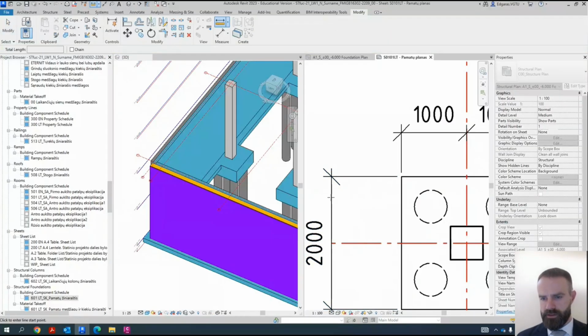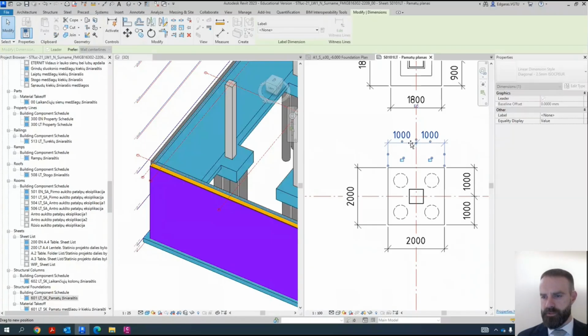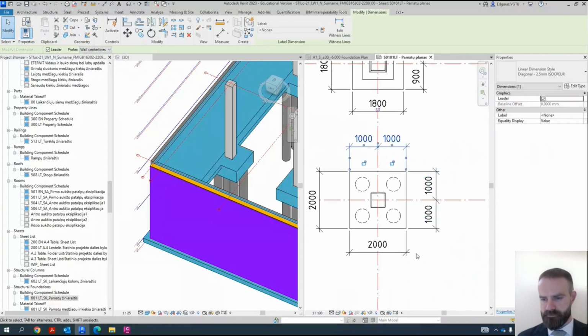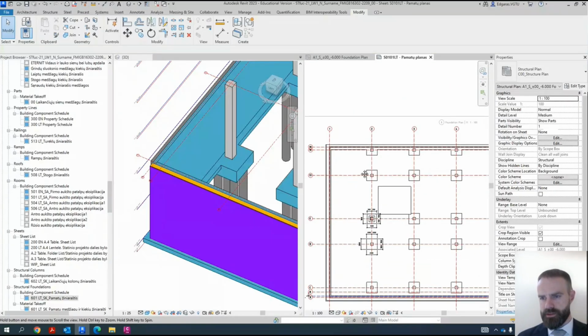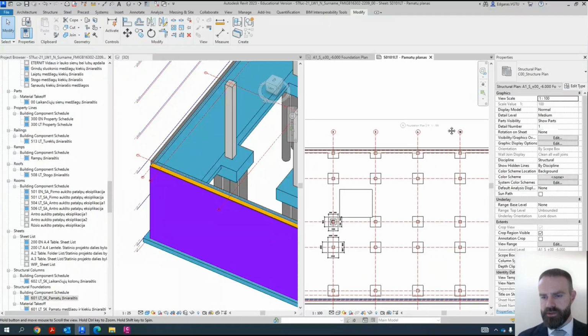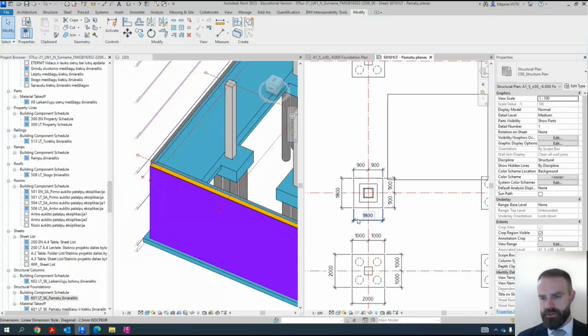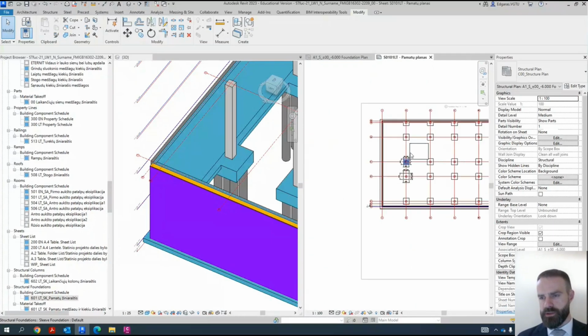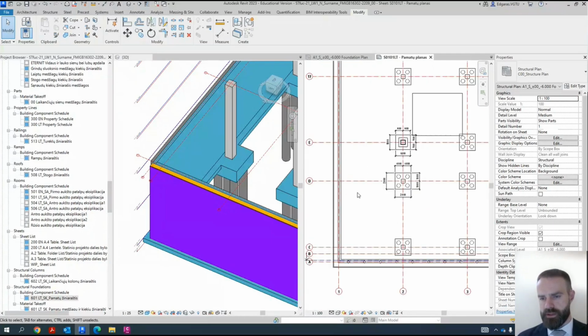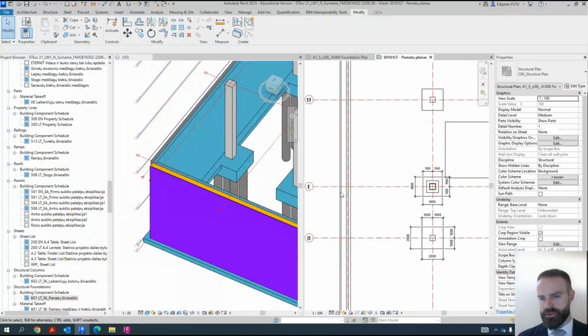And if I try one more time, about 10 millimeters from the object. So if your scale is, let's say, 1 to 200, it can be complicated. So in this case, you need to change the scale to 100 or 150 to organize all the dimensions nicely.